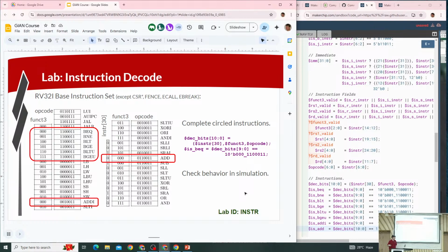So, as we're in stage 1 of the pipeline now, what we're implementing now, everything is in stage 1. We're just going to do everything in a single cycle. In that one cycle, we're going to process the entire instruction: decode, read the register file, go through the ALU to compute the result, write the result, all in one stage. After we get this functioning, then we'll stretch it out and implement a multi-stage pipeline.